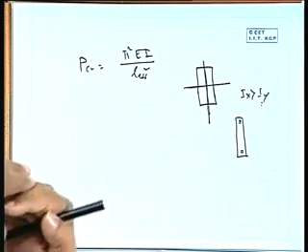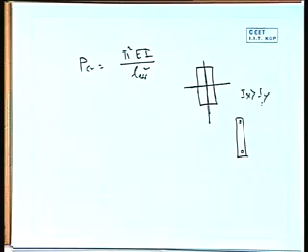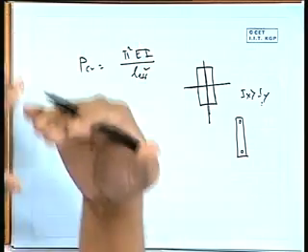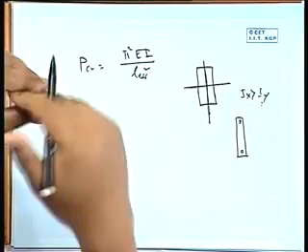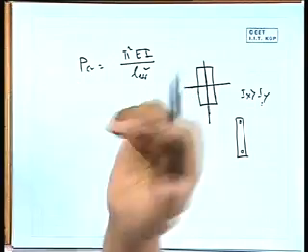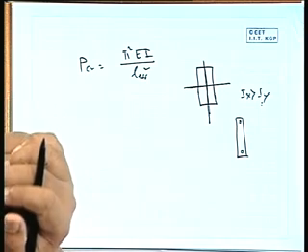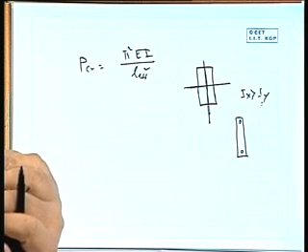So if you take the bending in that manner, it will be more or less a fixed support. So L effective will be 2L then. I may be less on this side, but L effective may be more. At the other end I may be more, L effective may be less. So we may get different combinations, and from there we have to find out which side it will buckle, right.